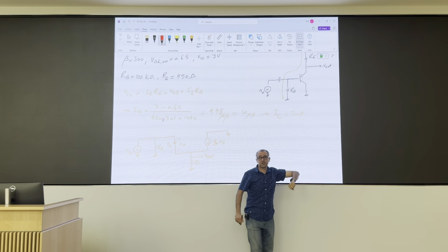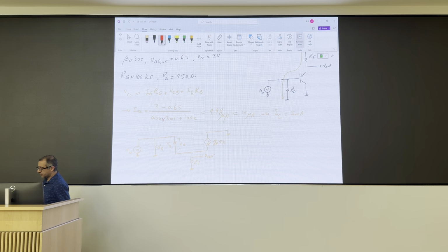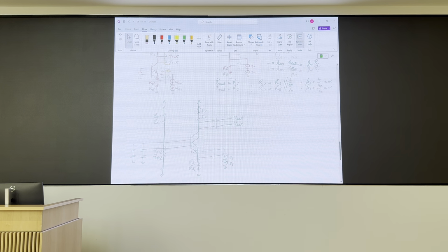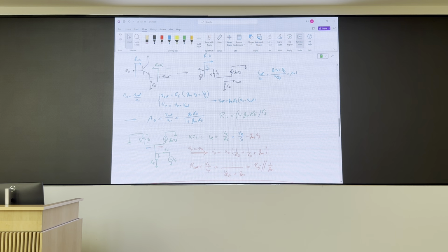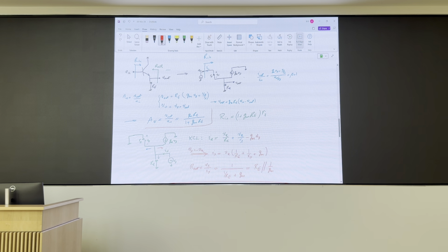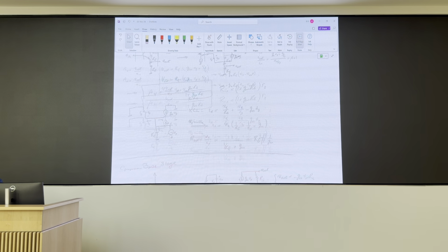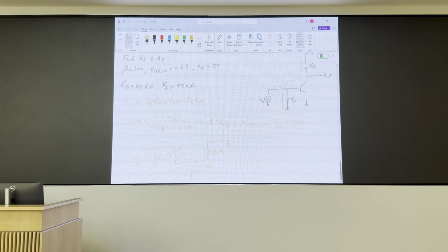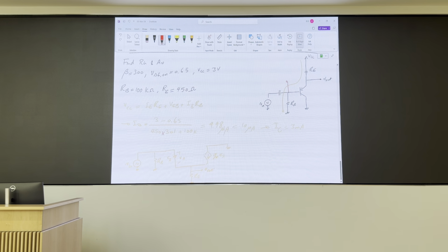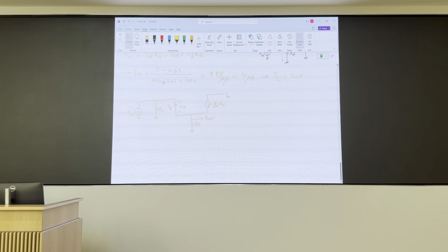So from the solutions up here, this is my gain, gmRE over 1 plus gmRE. So over here, if I call this VB, V out over VB is gmRE over 1 plus gmRE.